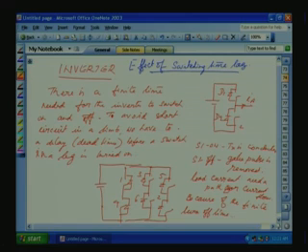Let us take a case. Now the transistor is turned on. Even though the diode is conducting, if you give the transistor gate pulse instantaneously, it can turn on immediately. Before the other device is turned off, there can be a short circuit. So even though the diode is conducting or the transistor is conducting, we have to give a finite delay before the incoming device is turned on.